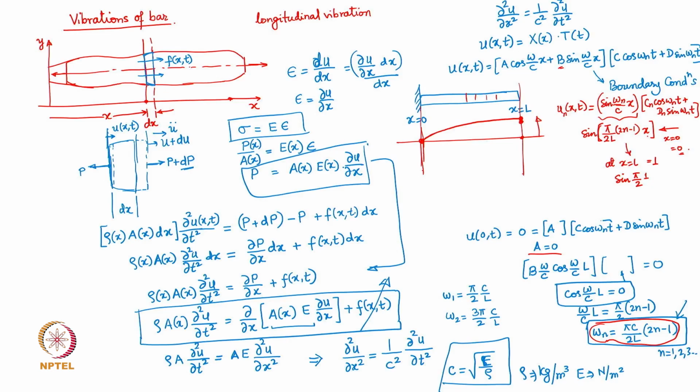It's just a way of showing that this particular element is going to be moving or stretching along the longitudinal direction by a value equal to this, in relation to a unit value at the free end. That's what the mode shape is all about, right? You show the relative displacements of each element of the vibratory system with respect to some reference displacement of one of the reference elements in the system. So that's basically the first mode shape.